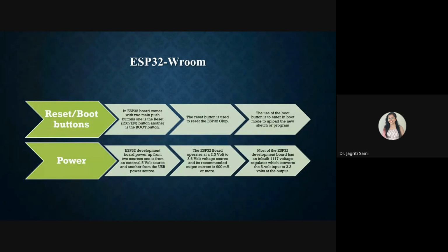On this ESP platform, you will have some boot buttons, enable buttons also. Same as I have shown you the reset button on Arduino Uno. Here you have two buttons. One is the boot button and one is the reset button. The boot button we sometimes need while loading a program on the ESP board, and the reset button is the same as on your Arduino. And the power options I have already discussed with you, that it works on 3.3 volt preferably.